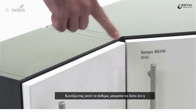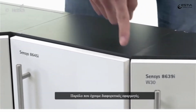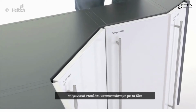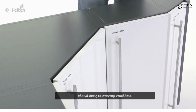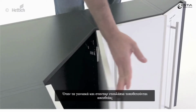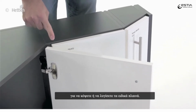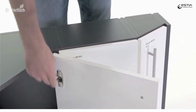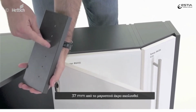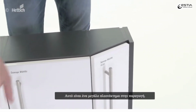Looking at this exhibit, you can see that the vertical reveals between doors are all the same, even though we have different applications. The corner cabinet was built using the same side panels as the standard cabinets. This looks quite nice when corner and standard cabinets are placed directly next to each other. You do not need to cut or edge band special side panels. Even the positioning of the mounting plate 37 mm from the front edge follows the common System 32 construction. This is a great advantage in production.